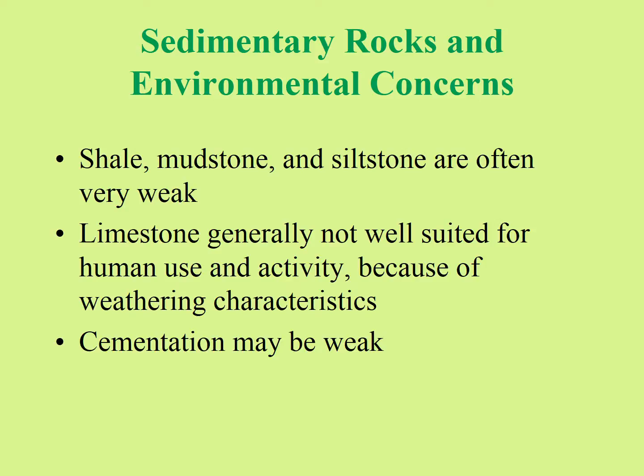Limestone is generally not well suited for human use and activity because of its weathering characteristics. If you have a limestone beneath your septic field, you are going to be dissolving that limestone more quickly as a result of the installation of your septic field, and that's probably not what you want to do. And it certainly is not what the regulators in your area would want you to do.